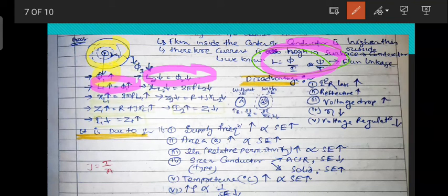If inductance is increased, then 2 pi fL, the formula of inductive reactance, is also increased. So by increasing 2 pi fL, impedance also increases. This increase in impedance reduces the current, and the decrease in impedance increases the current. By this process our current will become uniform.